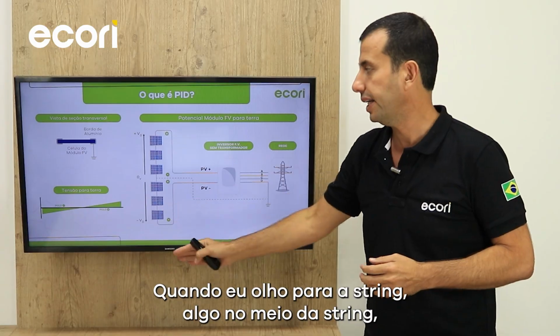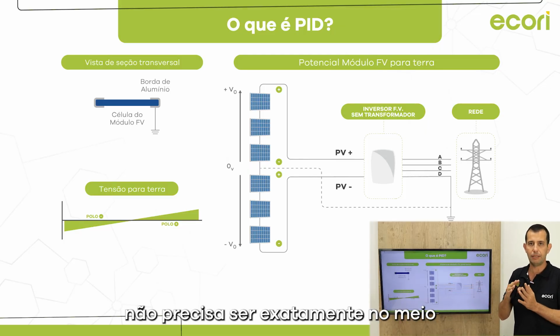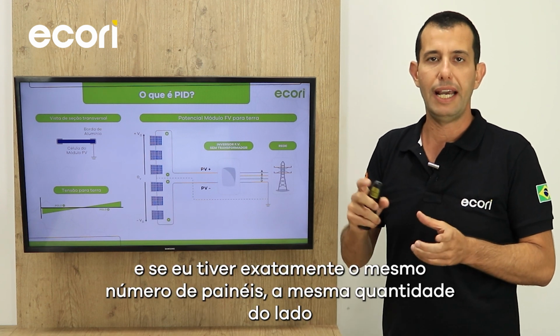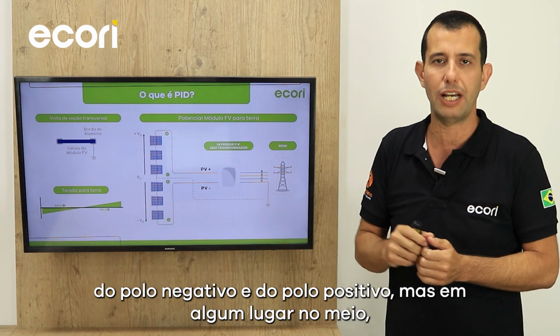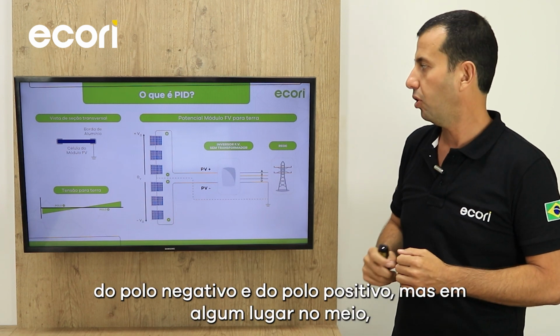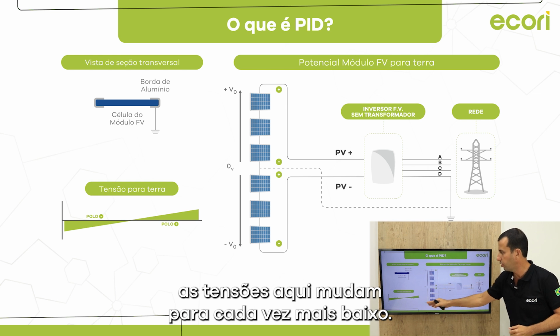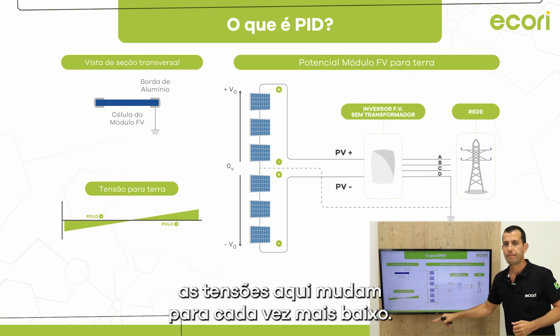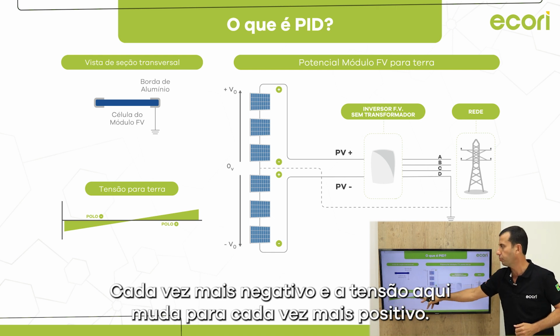When I look at the string, somewhere in the middle of the string, it doesn't have to be exactly in the middle, it depends on symmetry, and if I have an exact number of panels and all of them the same on both sides of the plus and negative poles, but somewhere in the middle I have some virtual ground. And compared to this virtual ground, the voltages here turn lower and lower, more and more negative, and the voltage here turns more and more positive.